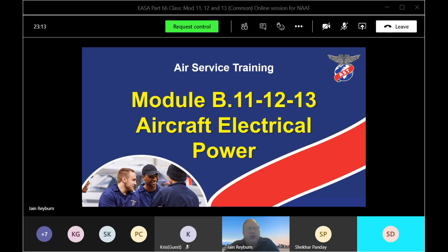Sometimes relays can flicker. If I have my positive here, positive, negative, and I put my current going through the coil, it can't go through that diode because that's the negative side there, that's the positive side there. Put it through there, my contacts will change over. No problem. Now if I switch this power contactor off, what can happen is we get something called a back EMF.